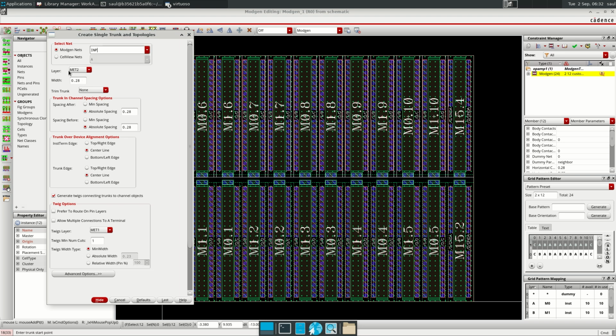The layer that we are going to route is metal 2, so I'm going to draw metal 2 connections that go all over the center here, connecting the net, the positive input. The width, by default, selects minimum width, but we should not use minimum width or minimum spacing for what matters, with the exception of where we place the transistors that close together. We should then use the minimum devices or minimum width for the connections.